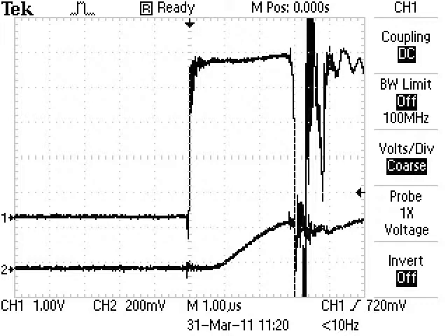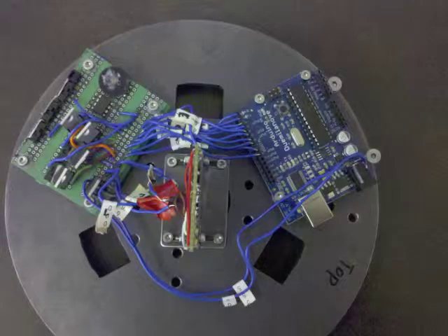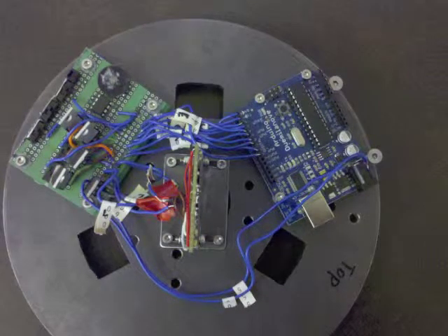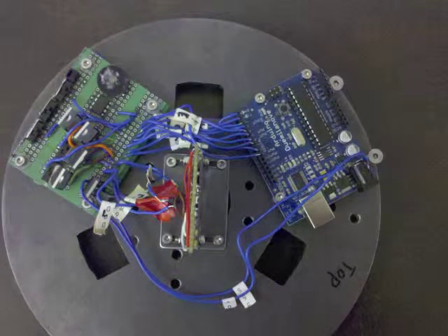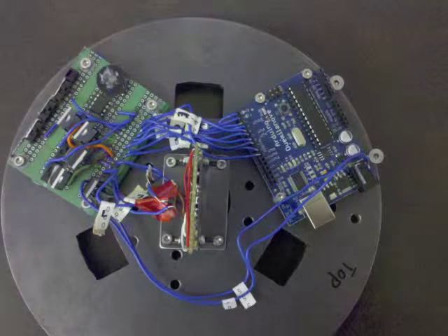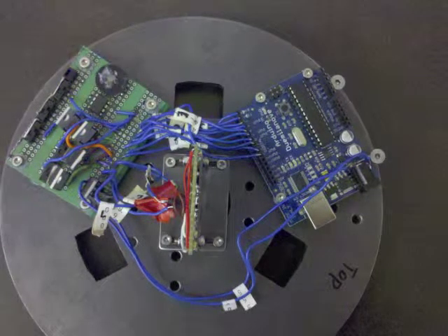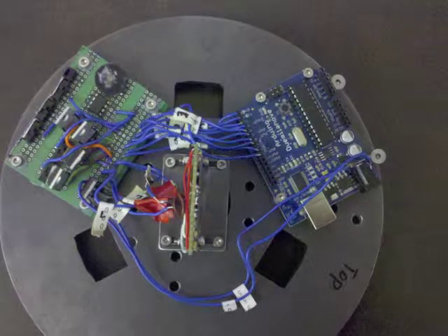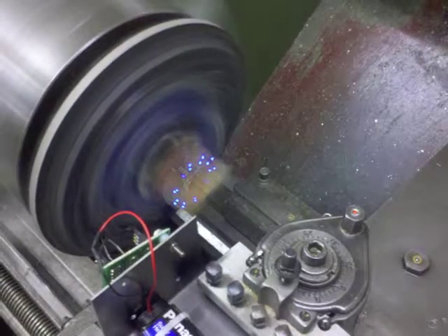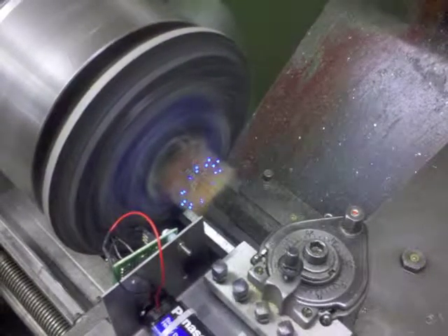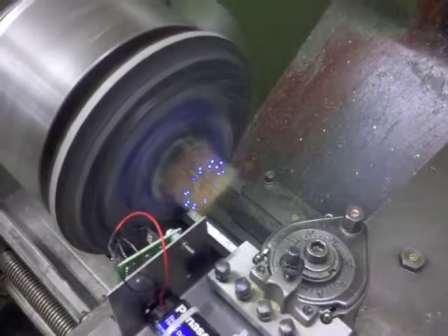project. To get proof of concept, we constructed a rig to spin some LEDs on a lathe. Using this rig, it was determined that pulses of 5 microseconds are capable of producing visible light. Furthermore, we determined that a 300 microsecond gap between pulses is sufficient to produce 2 distinct points of light. This was essential information since the limits of our system mean we must flash one frame every 328 microseconds to get 120 frames per rotation at 24 Hz.